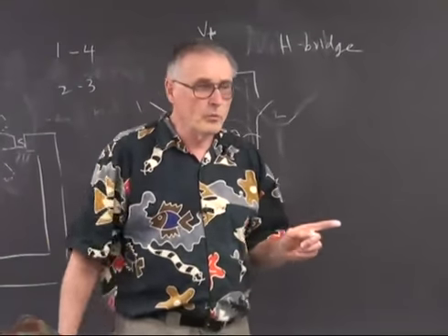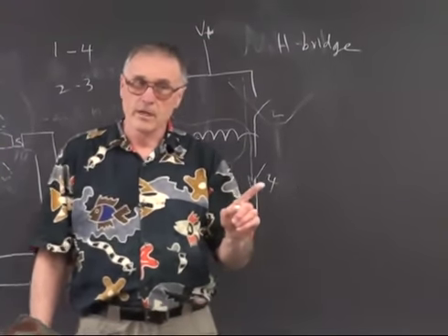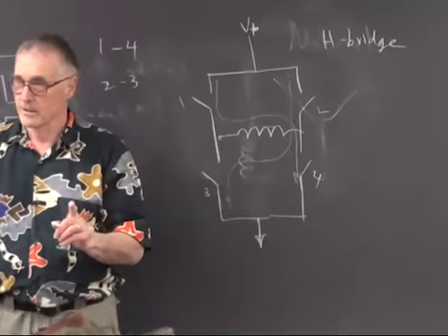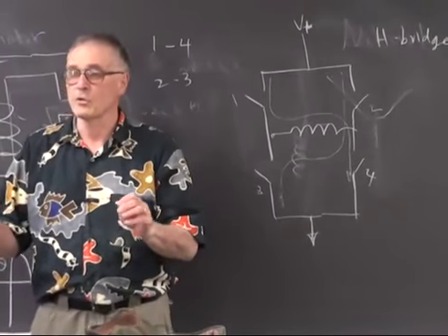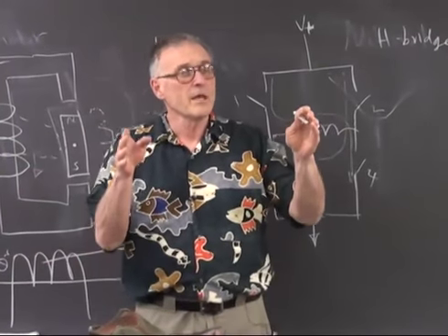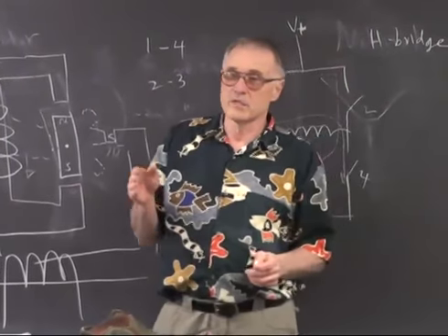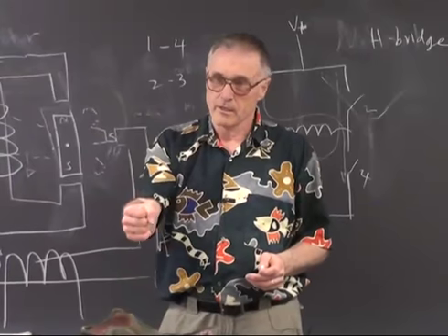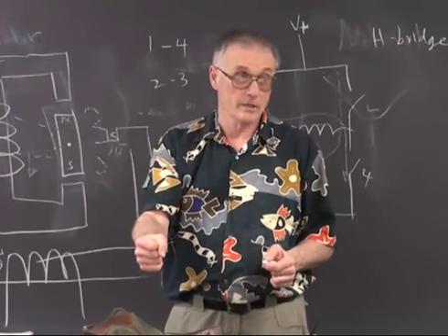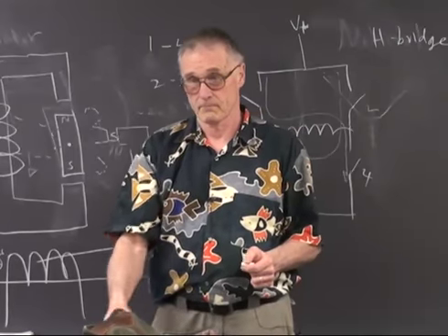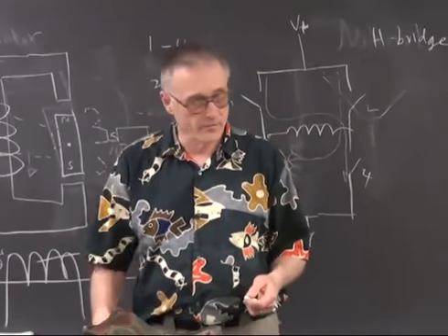You can run them open loop, you can run them digital accurate, as long as you don't exceed the torque limits, which means that as you accelerate, you have to slowly increase the pulse frequency, and you have to slowly decrease the pulse frequency. If you just go from 0 to full pulse rate, it's going to slip for a while, and you won't know where the motor is anymore, unless you have some sort of extra feedback.